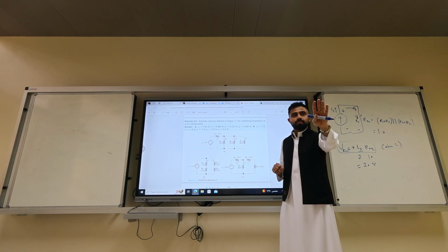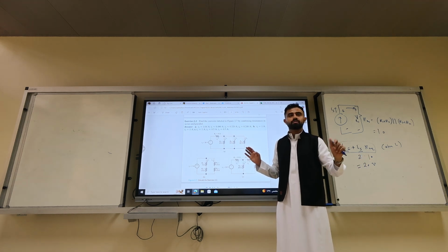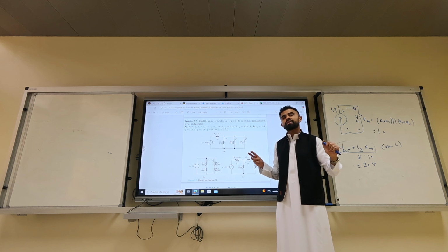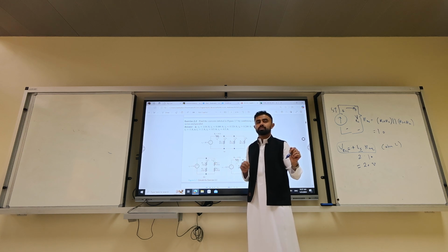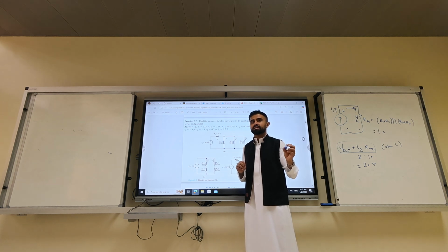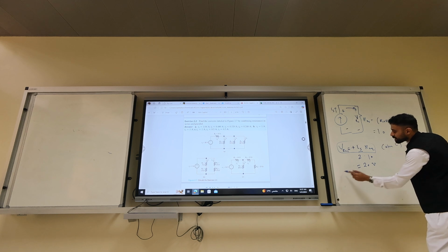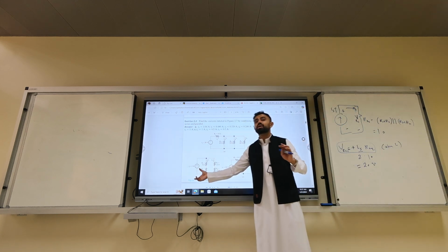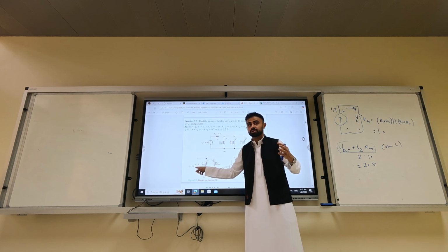I am not doing KVL because we're now mature enough to know if they are in parallel, they have the same voltage. You can do a KVL, but the question is you do not know the voltage drop across the current source. Well, if you want to do it, okay, what did I tell you about the current source? You cannot know the voltage, you do not know the voltage drop across it. So no need to do a KVL. This is a current source, it's not a voltage source.